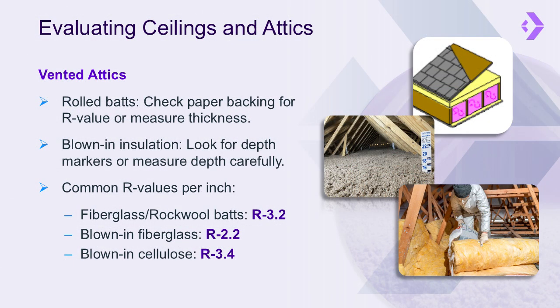Just like with walls, first confirm if there is more than one ceiling type to be modeled, and capture the surface areas and insulation characteristics of each. Most homes are insulated at the ceiling, with a vented attic above, and those are the easiest to get information about, so let's start there. Carefully find your way to the attic.